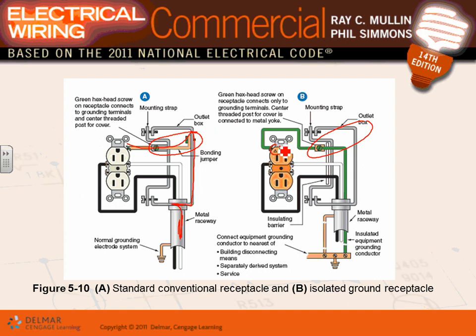What does that mean? Can you guys see the grounding slot here is not tied in any way, shape, or form to the box? And can you guys see where the green conductor goes? All the way down to the main panel. Who cares? By doing it this way, guys, when you bring your laptop and plug it into this receptacle, your laptop or server or cashier machines or whatnot will not be corrupted. Why?